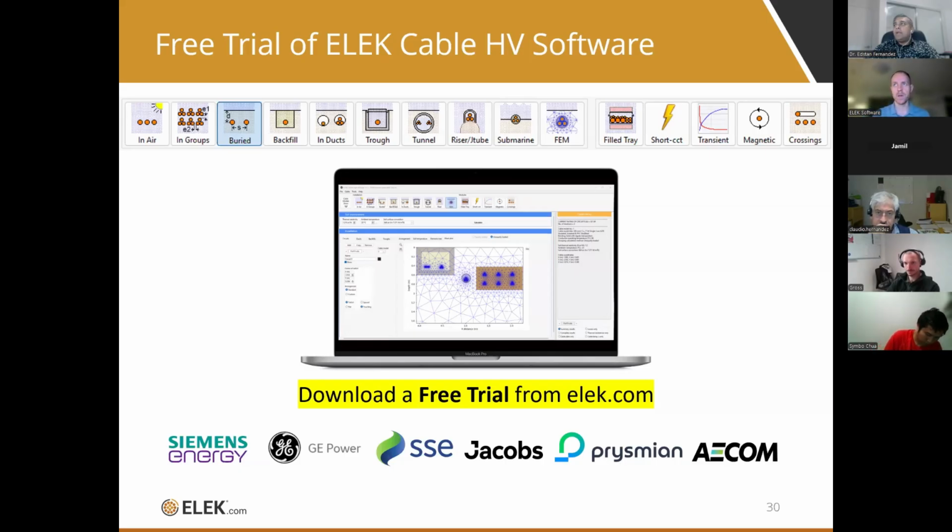I think we've answered a lot of questions. I'll take some that have been asked continuously, which probably everyone else could also benefit from. One question was about the maximum length that we can use for those HDDs, and what would restrict the maximum length. I think I explained that: mainly the pulling tension of the cable. The other question was about longitudinal heat transfer along cables, and how we can consider it in calculations.